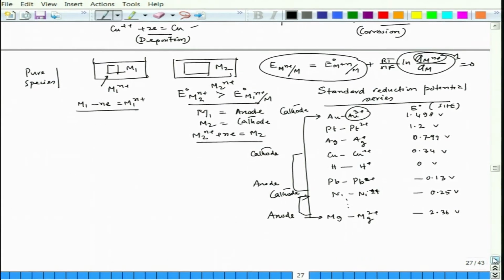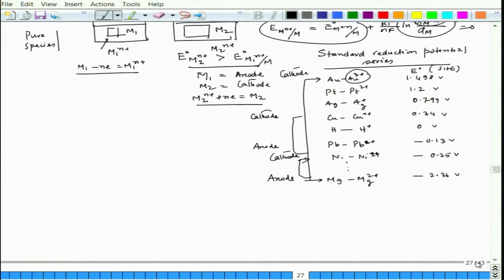So, that time we have to generate another series that is called galvanic series. In that galvanic series we have to just find out which one, in a two metal contact, is anode. Those two metals could be alloys, pure metals, or a pure metal and an alloy, all those combinations are possible. Even it could be the same metal, but the reactions would have different activity. Okay? I will come to that.